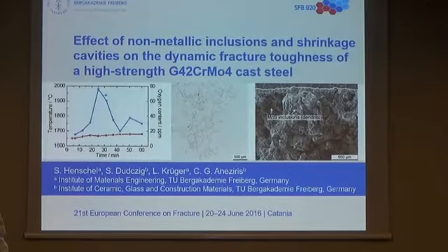So now let's have a look at the dynamic fracture toughness tests. You can see here that there is of course inertia in the first part of the experiment. When we compare the tup measurement, the force measured by the impacting tup, and the force measured by the strain gauge near the crack tip, we can see these differences here. But after some time, inertia effects can be neglected,